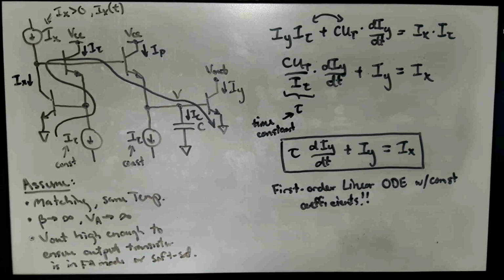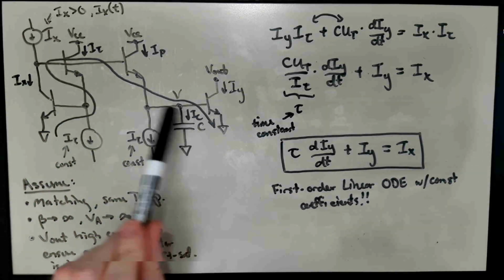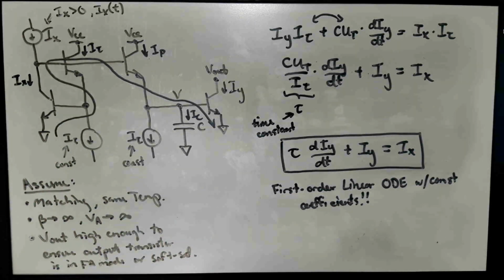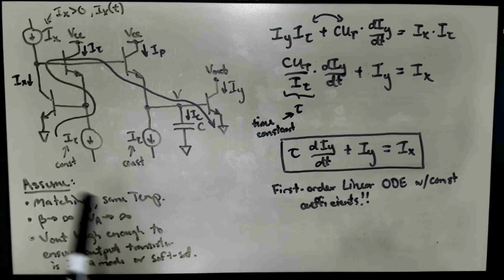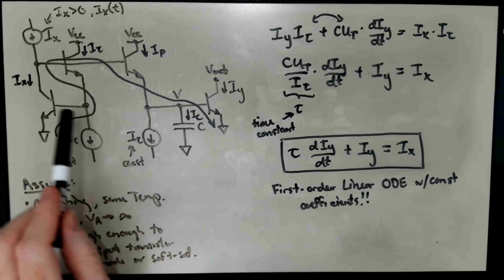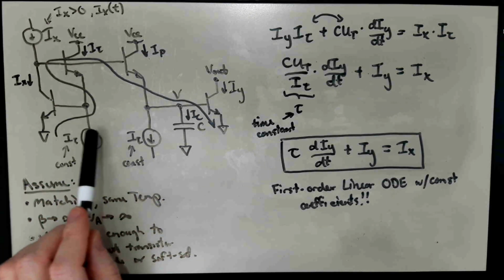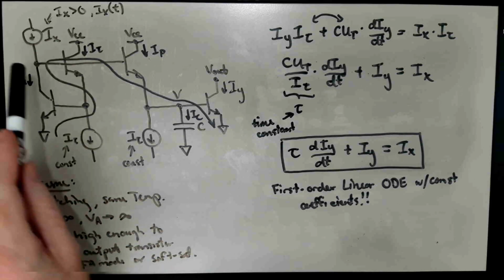So this is an end-to-end linear system from the outside, externally linear, but internally, if we were to look at, let's say, the voltage on this capacitor, if we put a pure sine wave in, we would notice it's distorted. It's got some sort of funky compression going on. But in this particular type of circuit, we use the nonlinearities of the transistor and the fact that they match each other and are very predictable in a coordinated fashion so that we can achieve end-to-end linear behavior.